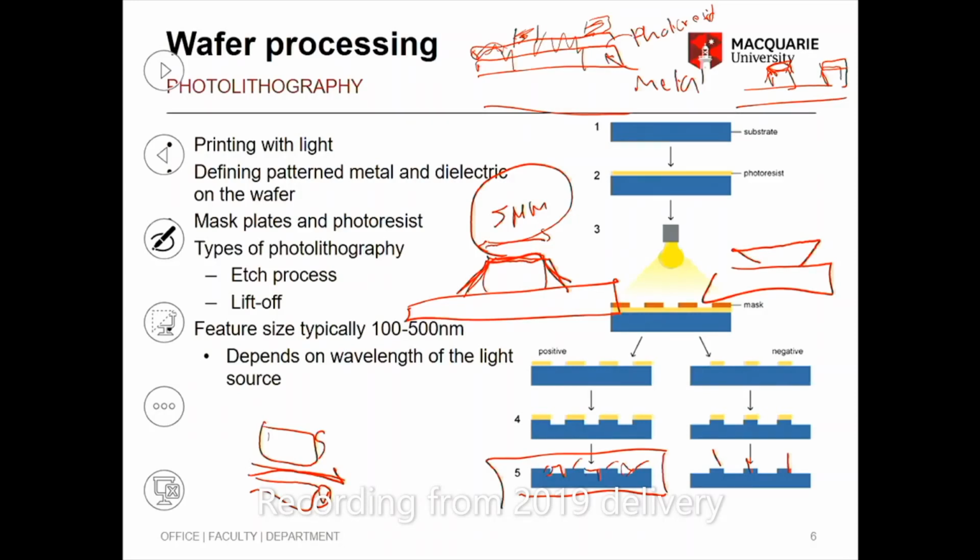They can do laser printing, the metal deposition. Because your process is 0.15 micrometer width, it's much smaller than 5 micrometers. Photolithography is a cheaper way. If you have to do optical printing of electrons in a metal deposition, it's going to be expensive, so they only do it for the transistors.